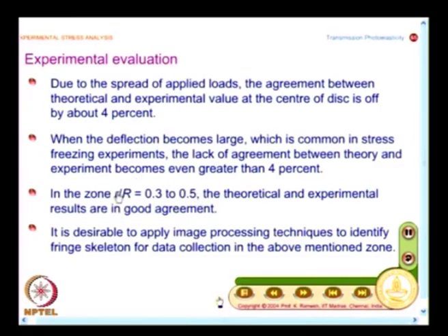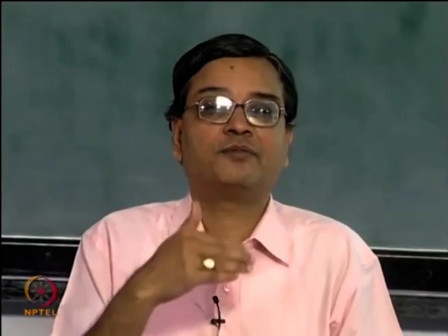in the circular disk. And as I mentioned earlier, when I collect a large number of data points, manually you will have to identify the center and then pick out data points. You may have to magnify the picture, pick out data points, and then do the calculation. It will be very time consuming. On the other hand, you simply go and click the cursor at selected data points, and your computer automatically understands XY position and also the fringe order. Do not you think it is a very simple approach?